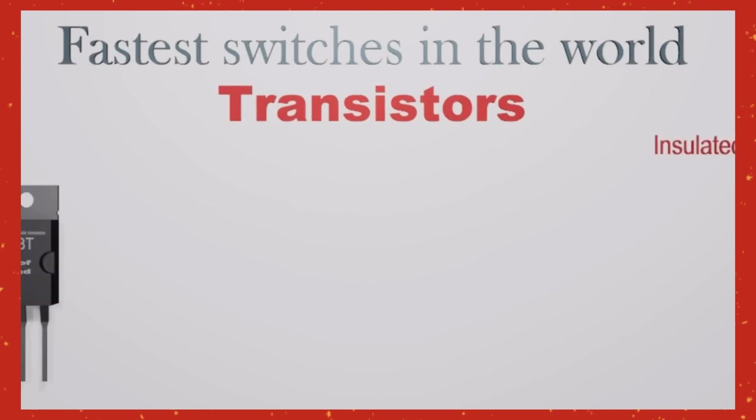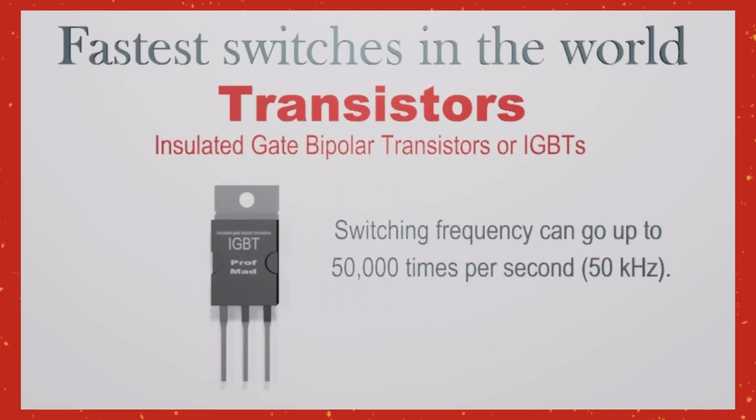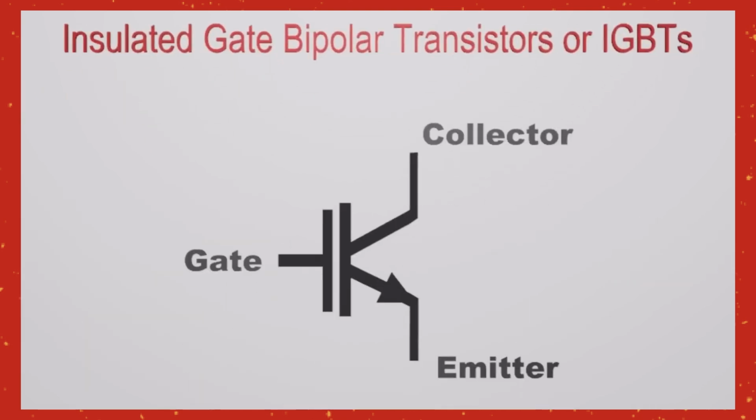At its simplest, an inverter consists of what is known as an H-bridge arrangement. This circuit illustrates the implementation of a single-phase H-bridge circuit using 4 IGBTs. The operation of the H-bridge is straightforward. By closing A and B and opening C and D at the same time, current starts to flow through the bulb from left to right.